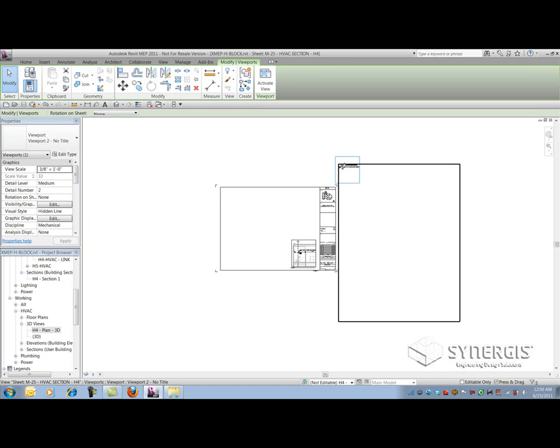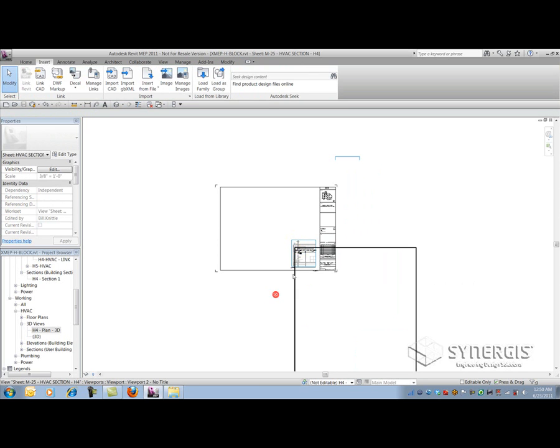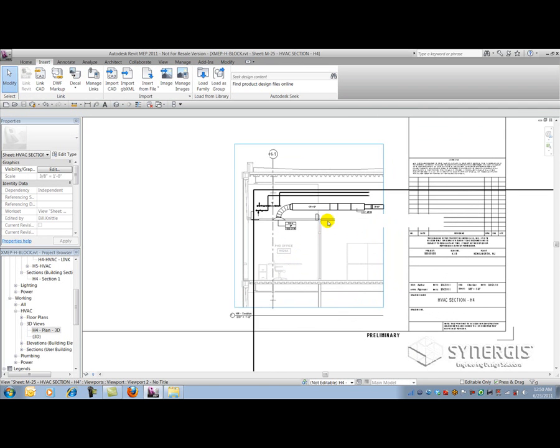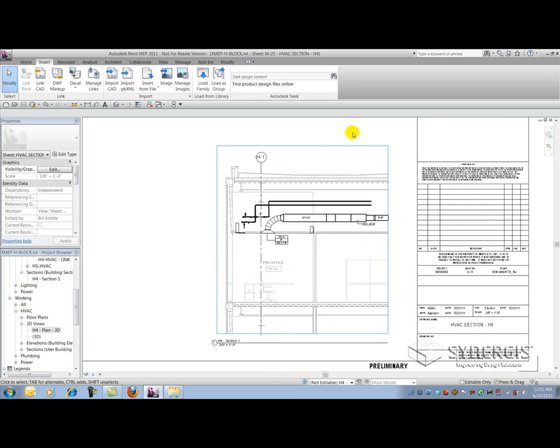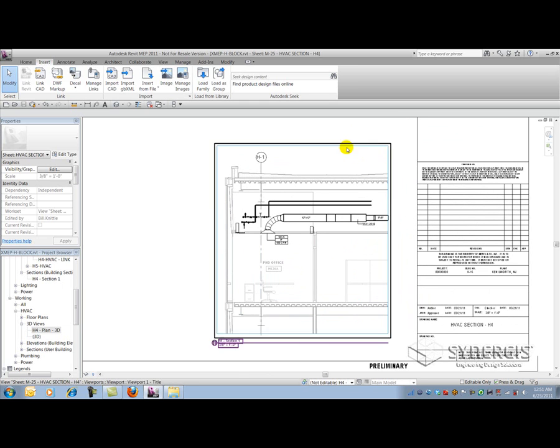So I'm going to drag the 3D view over top of the 2D view. And what's really interesting is if you work it, you can actually get Revit to show these alignment edges properly. So I'm looking for this horizontal alignment and vertical alignment, which is indicated by these dashed lines here on the screen. And when I let go, I should get a perfect match. So there you can see I've composited the two views together to make the final product. And this is sometimes the things we have to do to make things look right coming out of Revit.